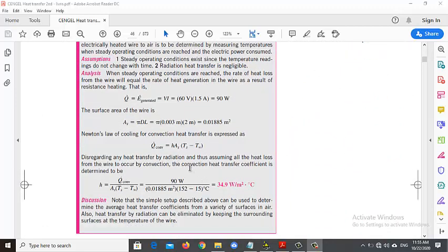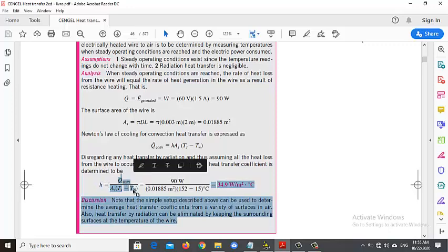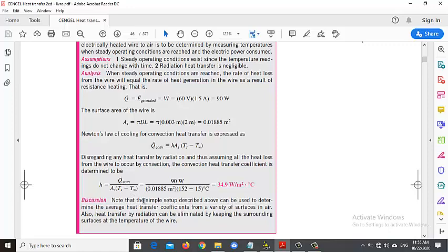What we're really interested in is this formula to get this working. You can see from this formula that the coefficient of heat transfer is H, while the heat transfer by convection is Q. A is the surface area, T is the surface temperature, and T infinity is the surrounding temperature. So H is the output because it's going to be the answer from these inputs when they are computed. Every other thing on the right hand side is the input. So we're going to model this using these given values to see how this heat transfer coefficient changes with change in surrounding temperature.